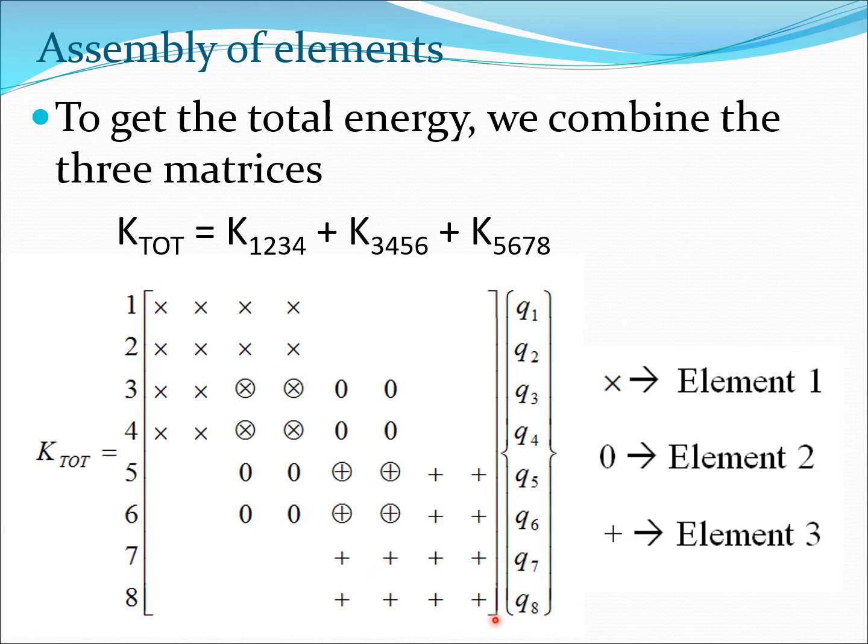So now this kind of matrix which you often get in finite element analysis is sometimes known as a banded stiffness matrix, because a lot of these elements are essentially zero. So all these elements are zero here. That sometimes makes it simpler for doing some numerical calculations and also for storage. You don't need to store the entire matrices in some cases, but again that is typically done in more complicated programming of large systems. If you are dealing with a simple rotating beam type problem, you may not need to practice some of those techniques.